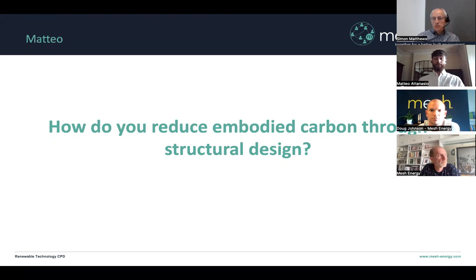Then you've got building efficiently, which is obviously having highly utilized structures as much as you can, and carbon efficient materials where you can. There's a bit of a duality, unfortunately, between having highly utilized structures, but also designing for adaptability in the future. So if I'm designing an office block that in 50 years time is going to be redesigned as a cinema space or a dance floor or something like that, the loading requirements change. And so if you've designed that to within an inch of its life and it's working very, very efficiently, you don't have that adaptability in the future. So it's a difficult position to be in when you're designing, to try not to over specify the amount of material you're putting into a building, but also to try and allow a little bit extra, and that's a question, I guess, for the audience as well.